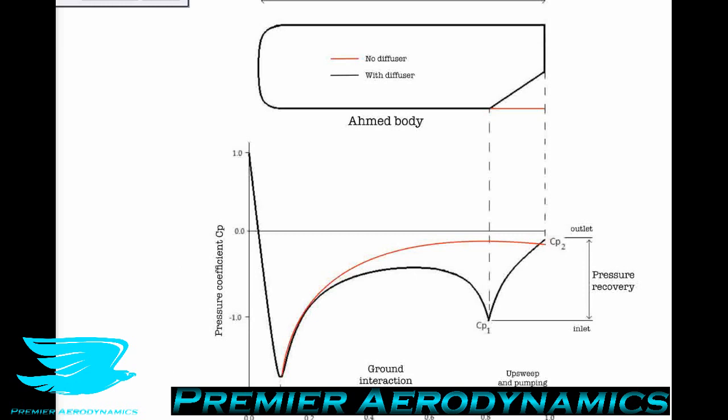Then as we progress towards the rear of the car, the pressure coefficient steadily rises until it reaches almost the pressure coefficient of 0. You can see here the red line is almost plateauing and asymptotically reaching 0. When it reaches 0, we say that the flow has fully recovered. This fully recovered means that the flow effectively matches the free stream flow pressure and speed. In reality, we can never really get a full recovery in anything really,